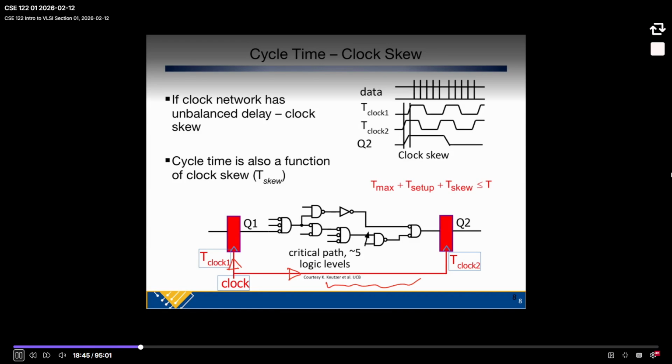In that technology, did they eliminate the skew completely? Or, back then, did they eliminate skew? No. They did not eliminate skew completely. There were still wires. You still had to go from these giant drivers to the actual latches, and that was still different. But not as different as having a buffer tree. Yeah.